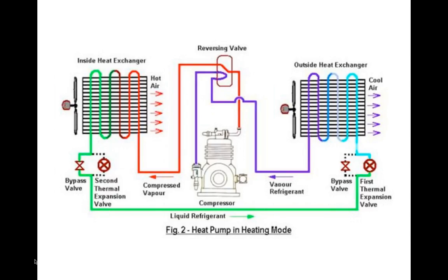I'm not going to get into too much detail, but heat pumps, the way that they work, remember that window unit air conditioner? You got hot air blowing out the back of it because you're taking heat out of the air. You got cold air blowing out the front of it. If you took that unit and turned it all around, you'd be blowing hot air into the house. So you could use outside air, even if it's pretty cold outside air, to heat the air indoors. Heat pumps do exactly that, except they do it with valves. So the evaporator coil now becomes a condensing coil and provides heat to the home. And the condensing coil becomes the evaporative coil. So you absorb heat from outside to move heat into the building in the wintertime, or change the valves again and move heat outside in the summertime.